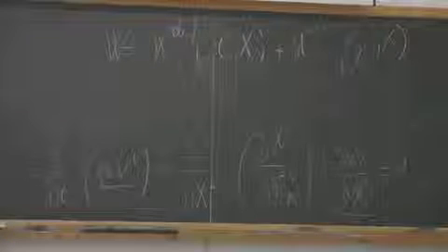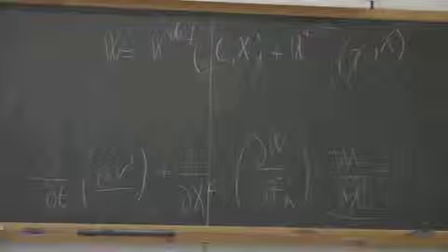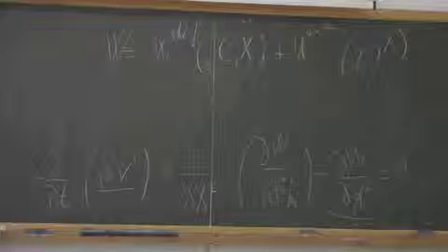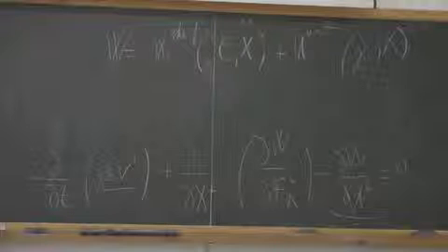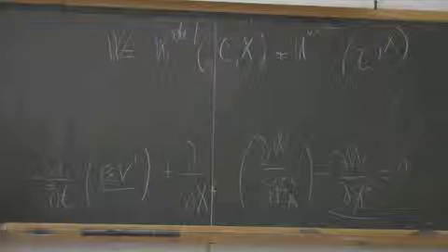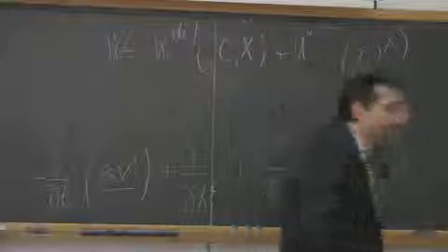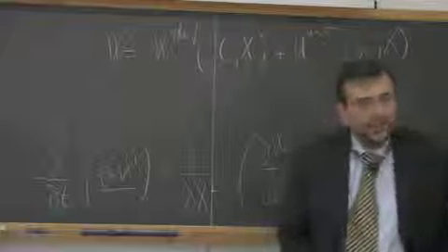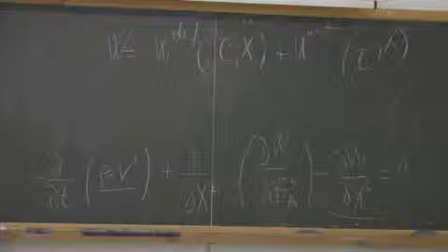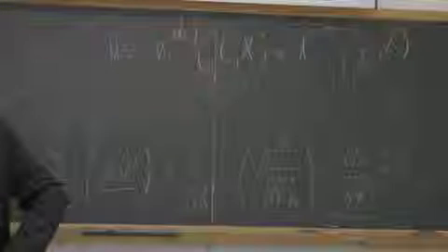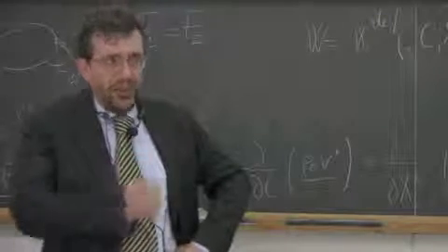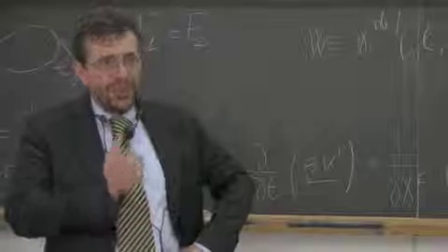Let me try to see if, when you split the energy into deformation and external one, and you take the deformation to depend only on C, you imply that this is the only way you can have objectivity from that? It is painful to prove. I didn't want to tell it. Okay, yes, but it is not so easy. You need theorems of representation. You can ask, given a scalar quantity depending on F, which is the most general function which is observer independent.